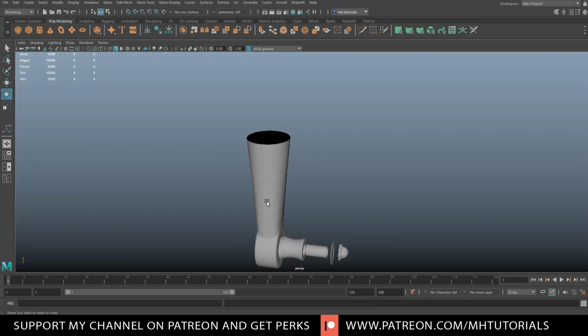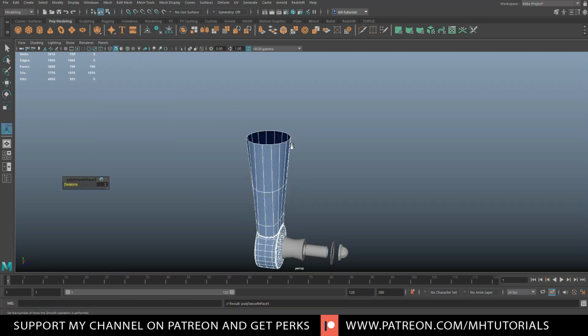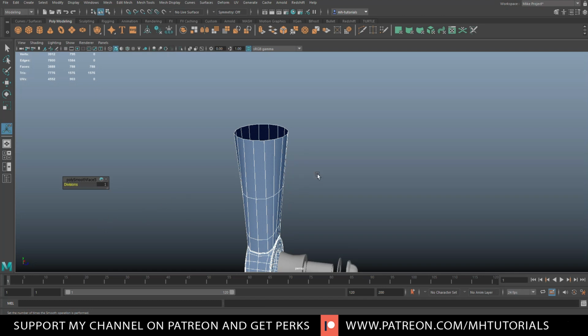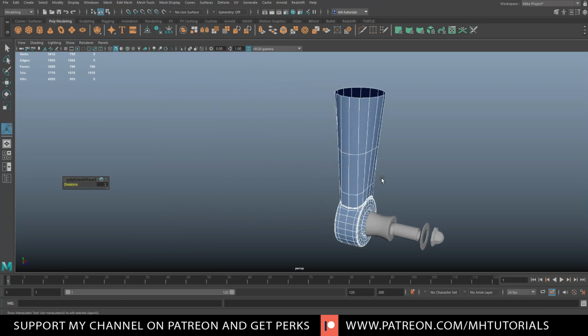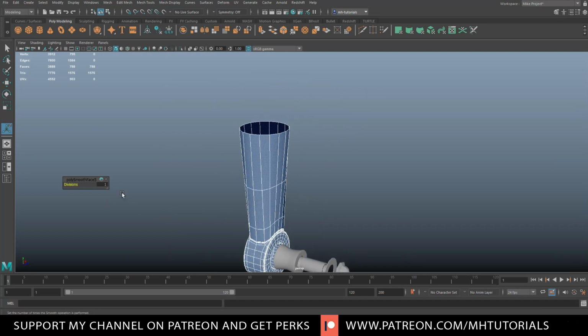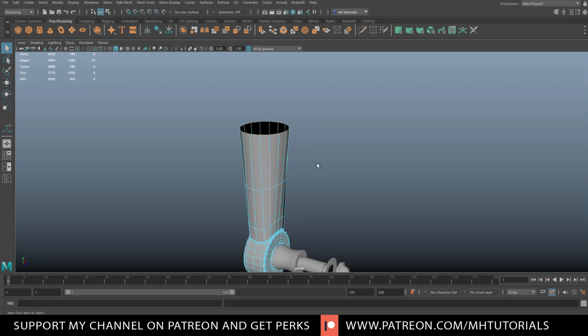Okay, we're going to work on this guy. This guy hasn't been actually smoothed out yet. So if I hit 1 to go back, you'll see that we've got this situation. So I'm going to go in here to mesh and smooth to actually smooth it. And now we're going to go in. Subdivision 1, I would say, is fine, unless it's too square, but I think it's okay. Yeah, so that's fine. We're going to go in here. We're going to right click at the edge, double click, Control E to extrude, R to scale in.